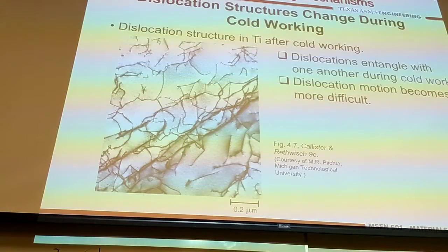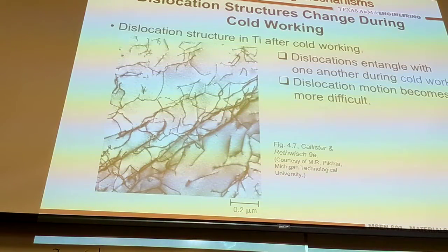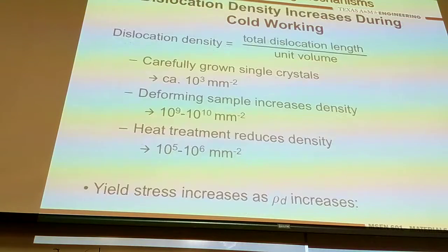So therefore you have a lot of dislocations. It's kind of counterintuitive, right? It looks like you want to stay away from dislocations. But what happens is that you're not just dealing with dislocation itself, you're dealing with dislocation motion. By generating a lot of defects that cannot move, that's fine. For example, if you think about dislocation density, the definition of dislocation density is the total length of dislocation, because dislocation is a line object.